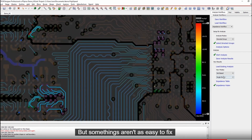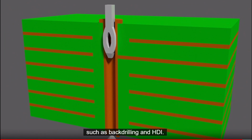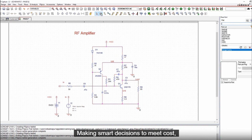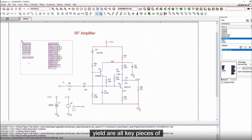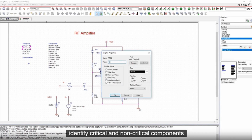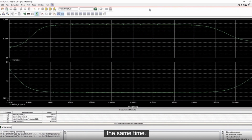But some things aren't as easy to fix within your layout, which is why you may need to use some advanced manufacturing techniques, such as backdrilling and HDI. With backdrilling, your manufacturer can remove the stubs to help limit reflection and impedance differences. Making smart decisions to meet cost, reliability, time to market, and yield are all key pieces of creating a good design. OrCAD allows you to easily identify critical and non-critical components so that you can improve your circuit's performance and reduce design costs at the same time.